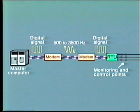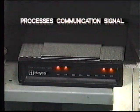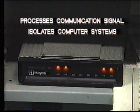Now remember, the transmission of data takes place in both directions. A modem is, of course, required at each end, the RTU and the master station. In addition to processing the communication signal, the modem installation should serve to isolate the computer systems and protect them from lightning surges which could occur in the communication link.